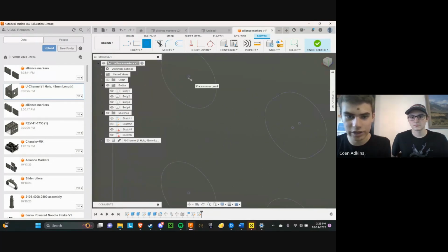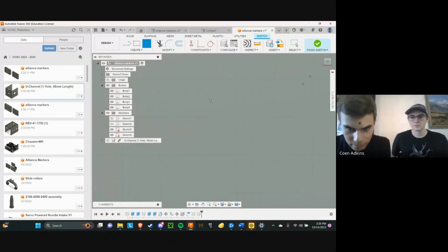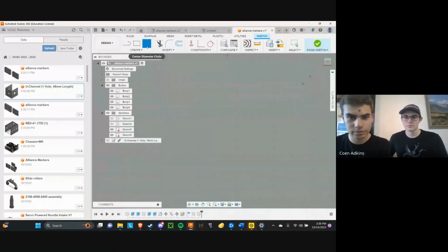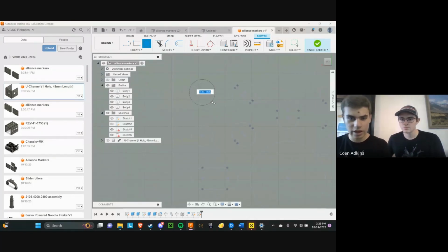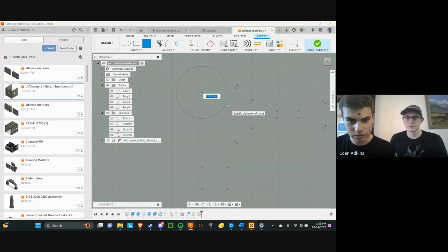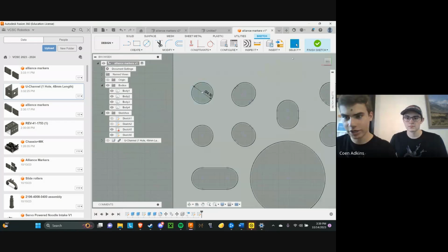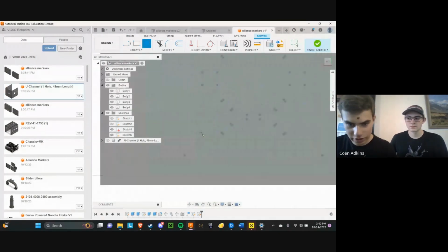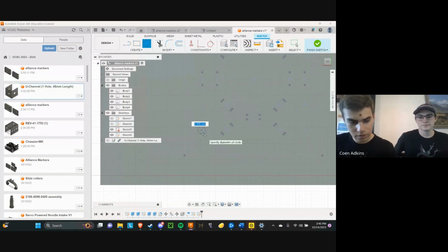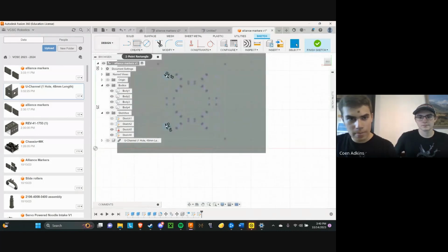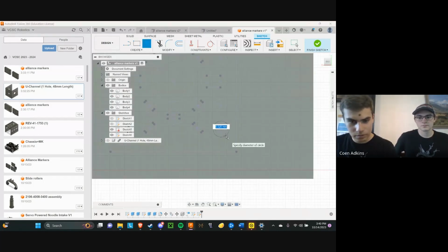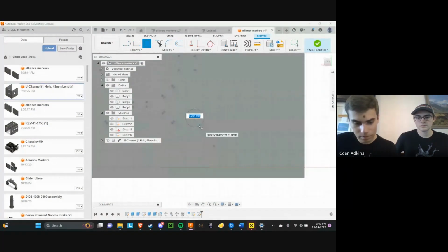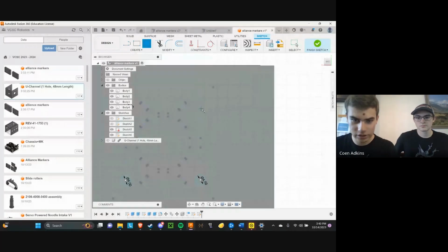So what we usually do is we align with the center of this hole. It's kind of difficult to see. We want to align with the center of the hole, and it'll snap into place if you have that setting on. And then you can adjust; for M4 screws it would be 4.5. Depending on your printer, that's going to change. And so you can do that for all the corners. And so here we're just typing in the number we want, so it defines the diameter.